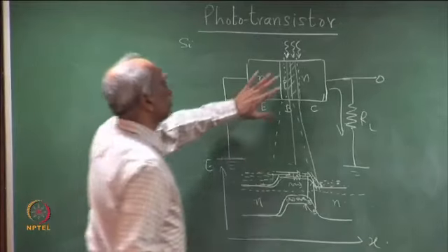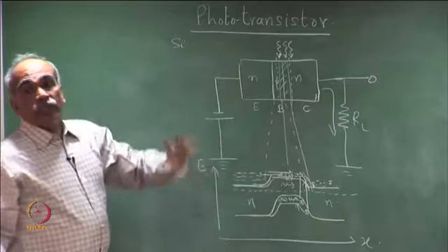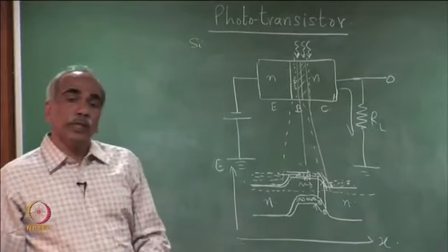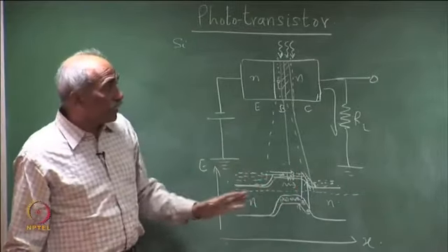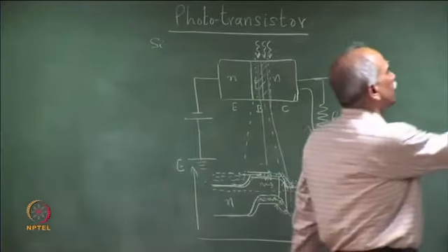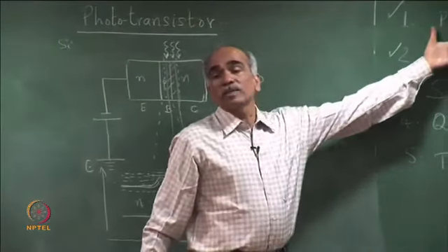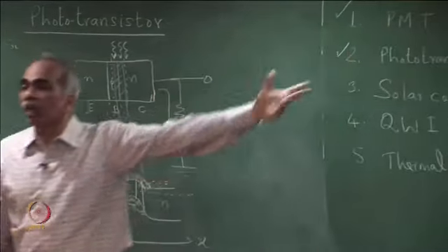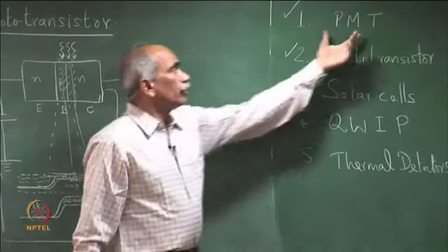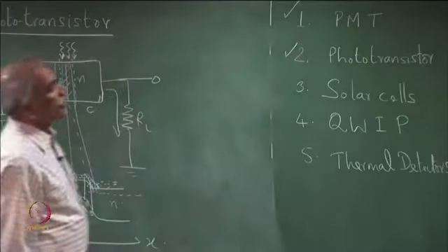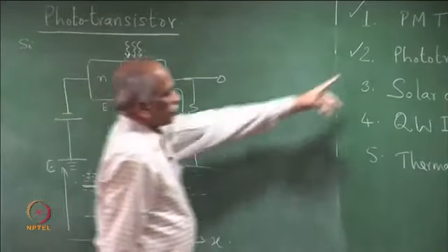And this is the primary working principle of a phototransistor. So, in the last class we discussed the avalanche photodiode, which has a current gain because of the avalanche process. Exactly like that, the photomultiplier tube has a large gain, again due to the avalanche process. It is not a semiconductor PN junction diode, but it works on the principle of photoelectric effect and avalanche process.